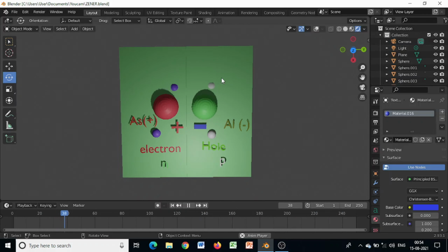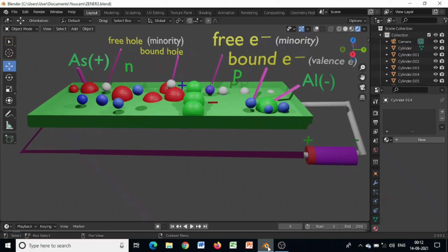The phenomenon of Zener breakdown was theoretically explained by Zener by quantum mechanical tunneling through the barrier at the junction. In tunneling phenomena, an electron confined by a potential barrier of height higher than the energy of the electron is shown to have a finite probability to pass through the barrier, and a finite probability of this electron is there in this region, just like this.